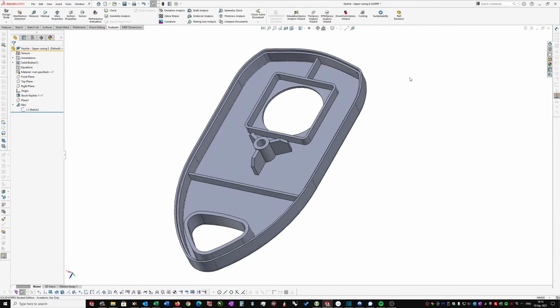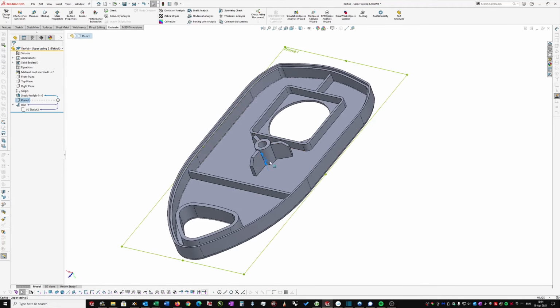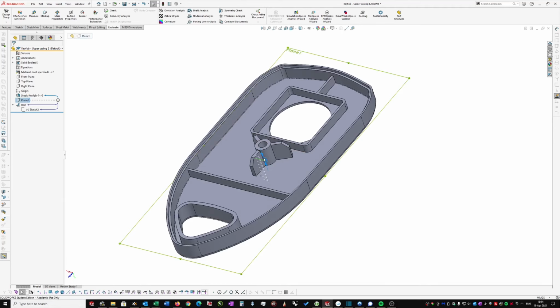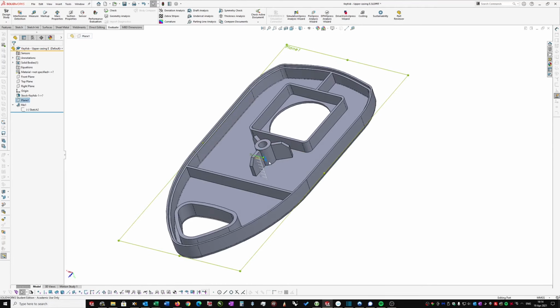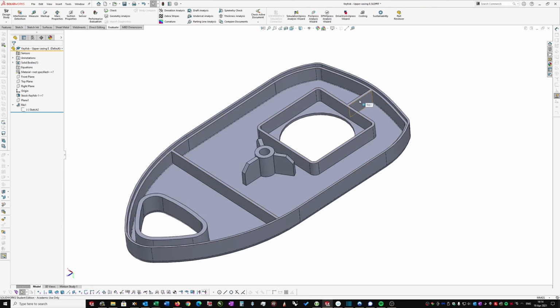And there's nothing wrong with that in and of itself, but when I tried to move this plane upwards, it would only get to the 0 point mark. And the reason for that is because since I've got an open-ended sketch, it has to go to a certain plane. And if I went beyond that plane, well, it just wouldn't do it because there's no plane to meet anymore. The sketch would be up to the limits of what's decided upon.